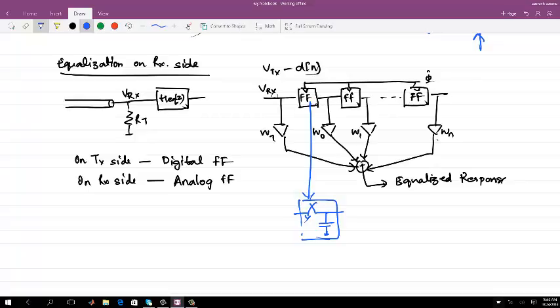That's about it. See, if you do not put any capacitor, what will you use to hold the voltage? First thing is, the capacitor will come automatically because you are having a real circuit. Another thing is, whether you want the capacitance to vary from one flip-flop to the other, or you want the capacitance to be fixed from one flip-flop to the other, or you want to design it such that you still hold the maximum of the voltage. So whether you need it or not, it will come automatically, but you need to have some uniformity between the capture from one flip-flop to the other.